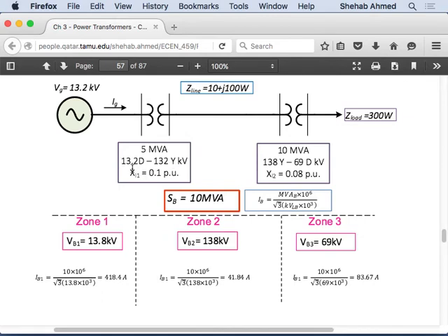No, it doesn't matter. You can start in the middle. You will have homework problems where they tell you to start in the middle. It does not matter, right? As long as when you go to the other side of the transformer, you choose the ratio of the bases to be equal to the ratio of the terminal voltages. If you do that, then the per unit equations work with us, and they allow us to eliminate the transformer, because the impedances will be the same from both sides.